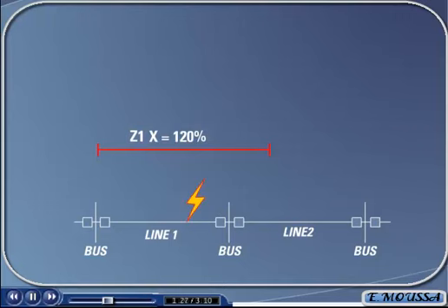Once a fault is detected, the relay will immediately trip the transmission line since there is no delay in the operation in the extended Zone 1 element. As you can see, the relay will trip the line even though the fault may exist in the area located in the extended Zone 1 but be in the adjacent transmission line.